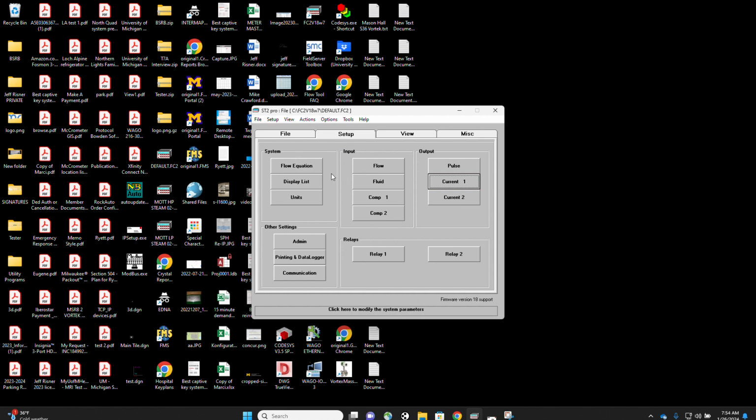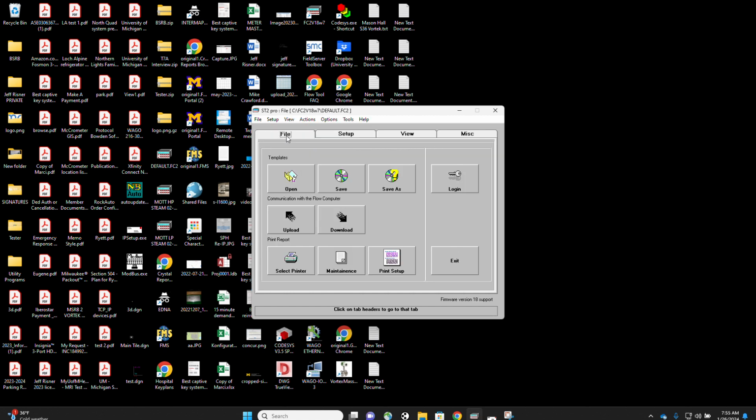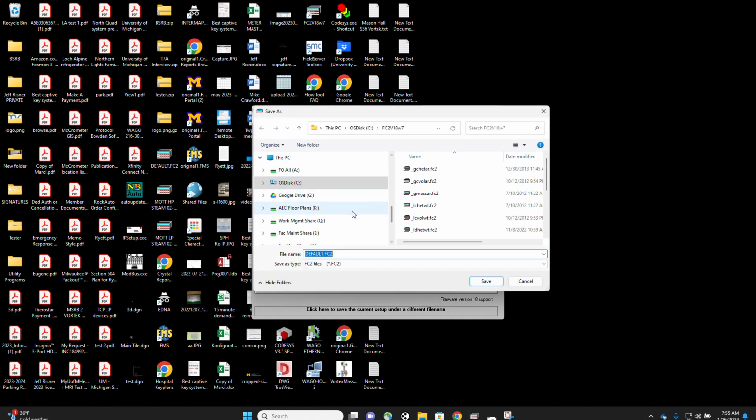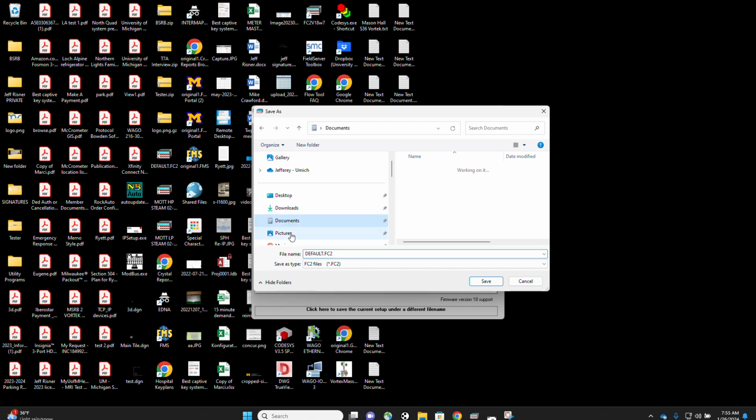actually I skipped a step. I skipped back here. Once you did the upload and click here to upload the setup from the unit to the PC, I skipped this, you should hit save as, and then find a location. I'm going to put it in my documents.